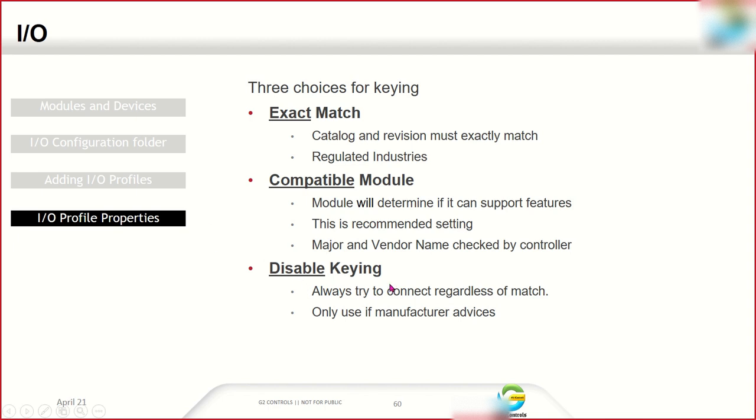you configure a different module in a particular slot, suppose you previously had a digital or analog input card, and you take an analog input card from a different manufacturer and just add that card into the slot, it will create an electronic clash, and it will be harmful for your system. That's why don't use disable keying. You can use it, but try to avoid using disable keying.